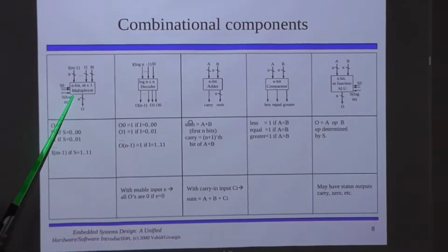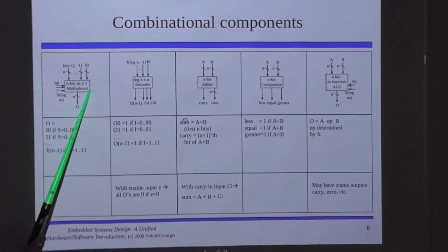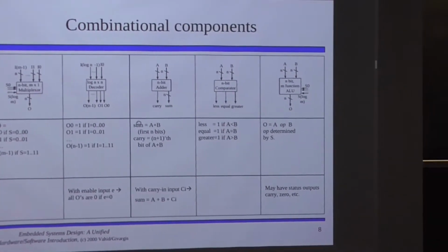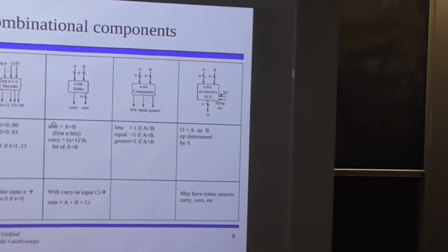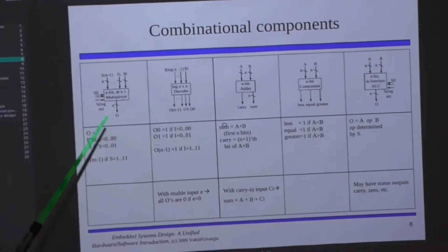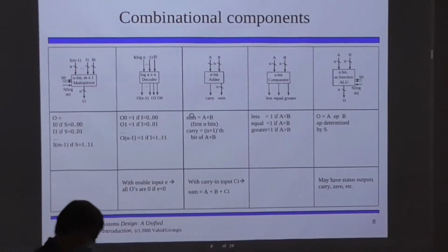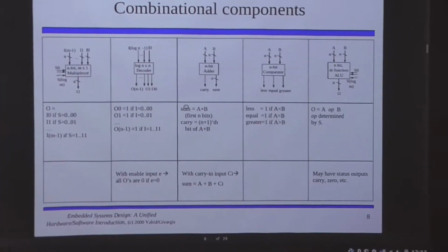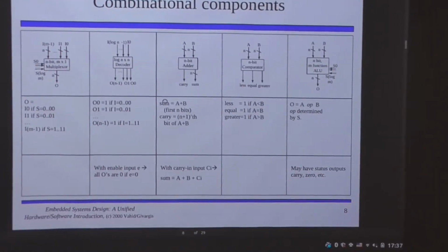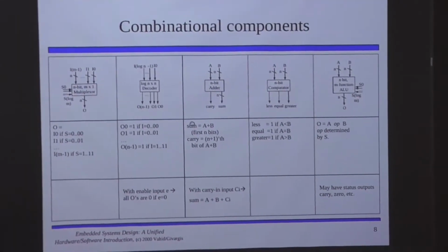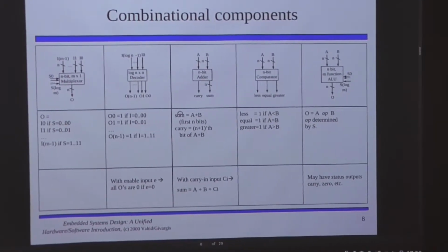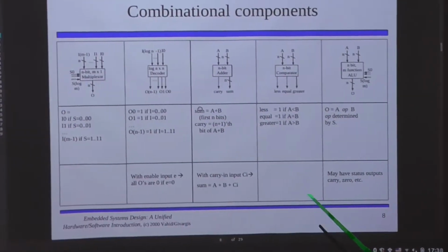Multiplexer, first of all, properly spelled with an E, not an O before the R, but okay. Requires a selector signal, right? Multiplexers are often used to funnel the correct input into either a register or some kind of adder or subtractor or comparator block, some other circuit, right? A selector signal is required for that. One of the things that we're going to develop during this lecture is the separation between the data path logic and the control logic. The data path logic is obviously the type of stuff we've been talking about so far. The control logic is essentially all of the stuff that we've assumed to have just happened up to now. So the selector signal for a multiplexer is going to be important.